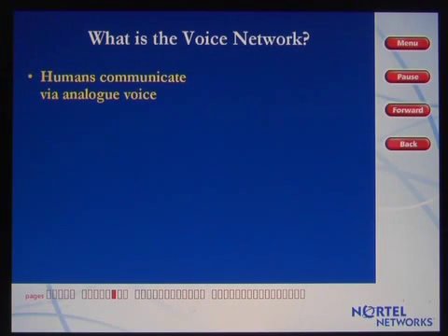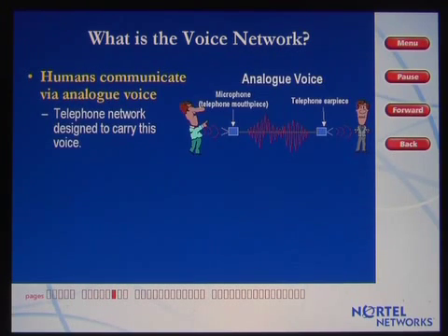Unlike computers, human beings communicate via voice. Voice is an analog, continuous variable waveform of communications, with information transmitted via different frequency waves. Telephones will convert sound pressure waves into an electrical analog signal (microphone), and electrical signals into sound pressure waves (speaker).